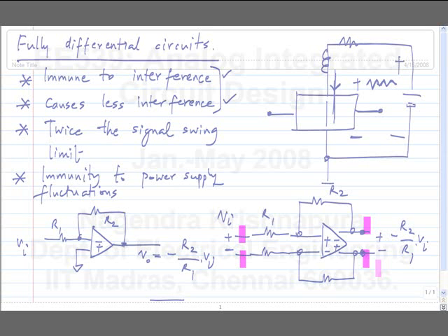Another way to think about it is, here we have one output voltage and we stabilize it to a particular value using feedback, one feedback loop. Okay. Here we have two output voltages. Now we can think of it as two separate output voltages or decompose it into differential and common mode components. The differential component is stabilized by this differential feedback network. The common mode component has to be stabilized by something else. It is known as common mode feedback and it is usually treated as something internal to the op amp. Okay. Because the signals that interest us are these differential signals.